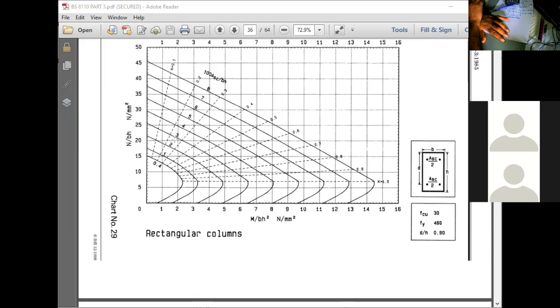Okay. Any other question like that? Excuse me, sir. Yeah. So in the first method, the N value, we need to calculate that, no? No, using the actual load. In the coupled shear walls, can you remember last time we calculated the axial load? Yes, sir. That is due to the moment, right? I mean, due to the lateral load. No, due to lateral load, you get axial load, but in addition to that, you get axial load due to the self weight. Yes, sir.